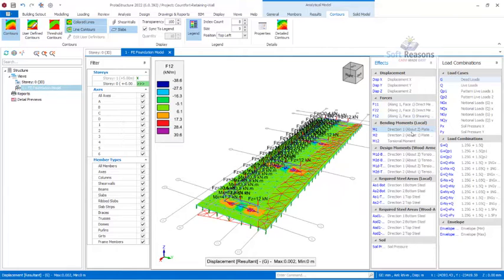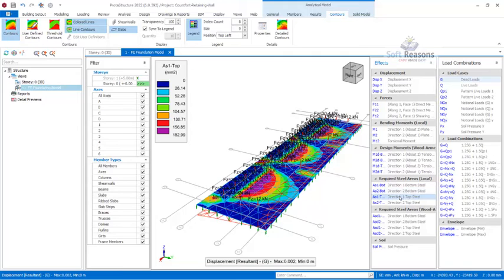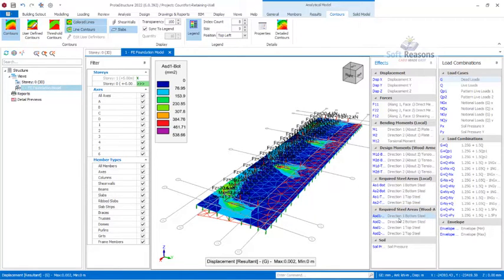So for the bending moment in the local axis, we can see right there. So get all of that selected to apply the effect. So it requires the area in the local axis. You can also see we have 525, which is somehow high, but the program will select the reinforcement size for us as we make progress. Let's continue. In the bottom two we have 192, all right, 182 for top one, and then 651 for top two right there. So using this, we have the area requirement, you can see right there.